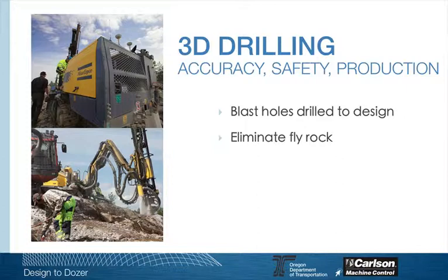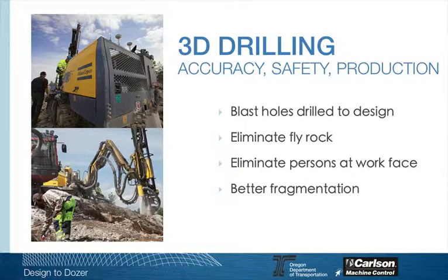All of the design holes for blasting are designed with precision by an engineer, and these blast holes are in a set grid. They are angled and parallel so that the blast is designed for maximum benefit. Some of the reasons for this are to eliminate fly rock, and also to make sure you get the desired fragmentation.